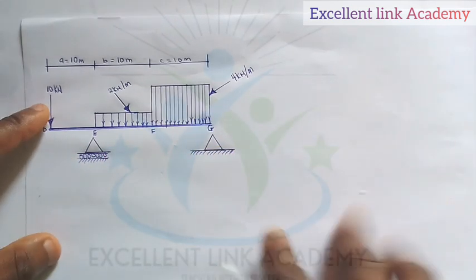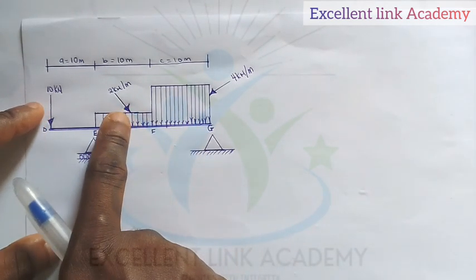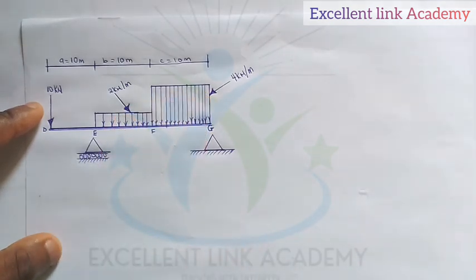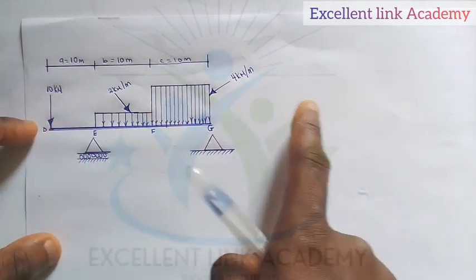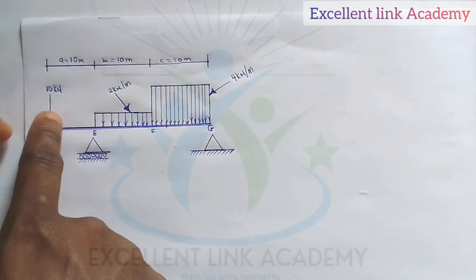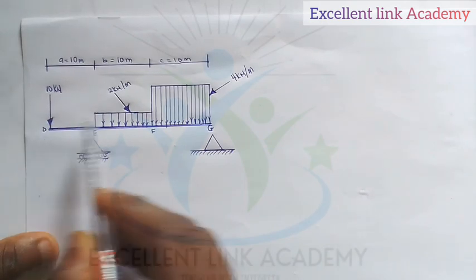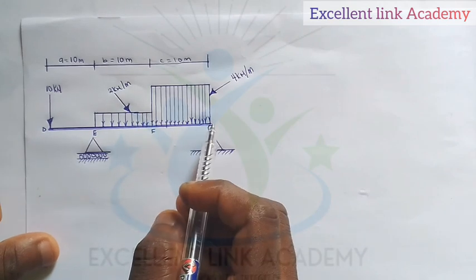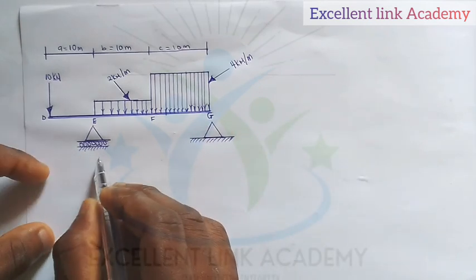Secondly, what I want you to notice is that this load you are seeing here is called a uniformly distributed load. These two are called uniformly distributed loads. This is a point load. Now, my first task says to make sure I convert these two into what? Point load, something like this one, this way. I need to convert all these two loads to what? To point load. Now, the first task says let's draw our free body diagram.